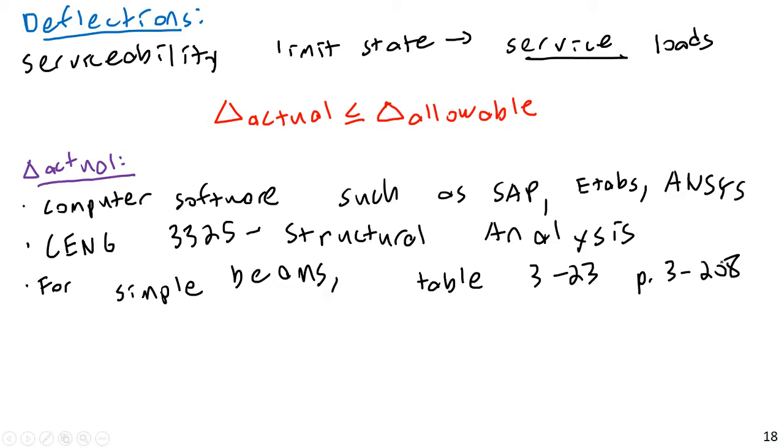And so that's the delta actual. But then what about the supply? Or sorry, that's the delta actual. In terms of demand versus supply, this would basically be your demand, and this would be your supply here, because allowable is what you're allowing. That serves the same role as the allowable applied load, the max moment, that sort of thing, your phi M n, that kind of thing.